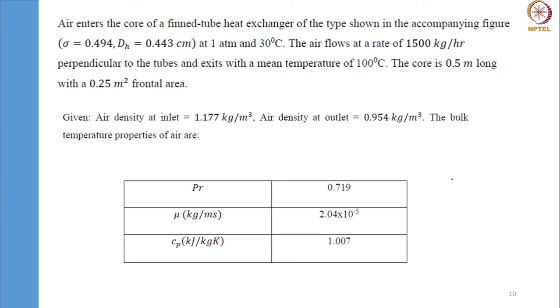At the inlet the density is different and at the exit the density is different, so as a result there will be a pressure drop. That's called momentum pressure drop. Of course there will be gravitational pressure drop too, but this is in a horizontal direction, so we neglect gravity pressure drop. So only the first two terms are considered, the frictional pressure drop and momentum pressure drop.